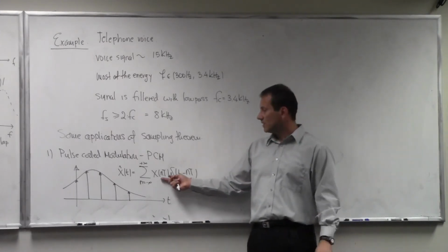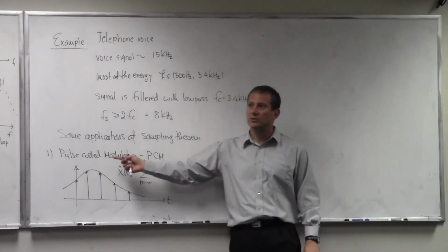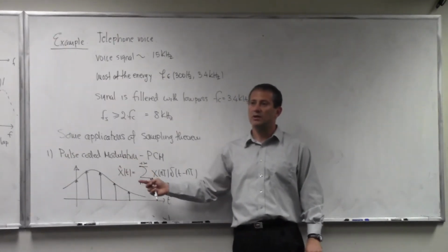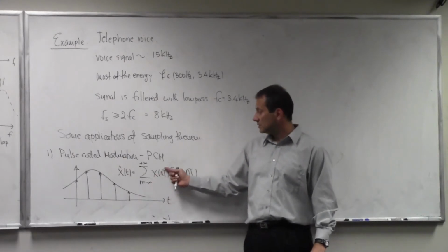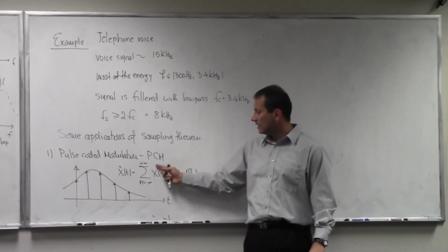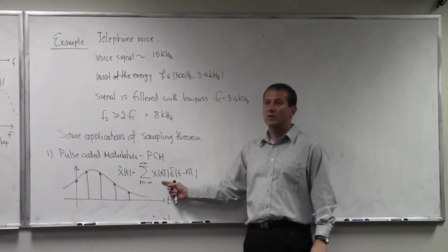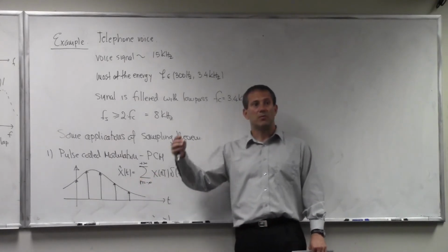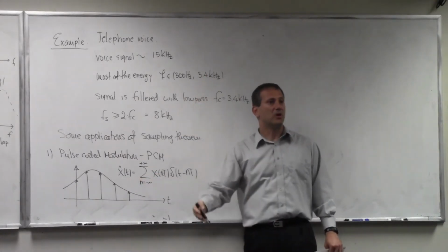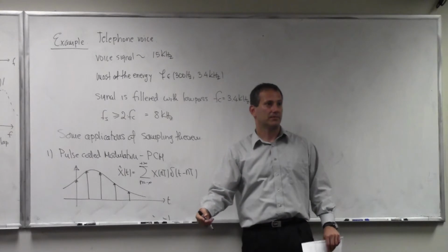So that means we can never accommodate a continuous range. We only accommodate a discrete range. So what that means is this x(nT) here is always quantized, meaning it is never a real number as it is sampled here, but one of capital N possible values, right?